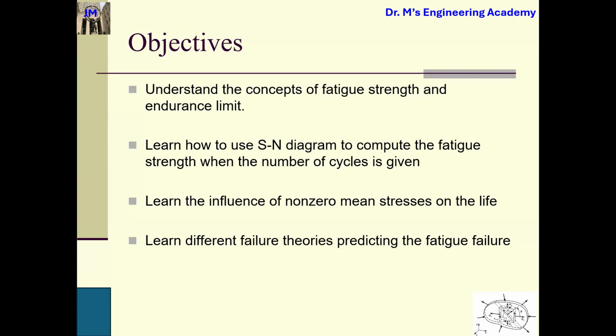For static loading, we compare the stress level with the yield stress level, and the critical stress intensity factor with the actual stress intensity factor. But for fatigue, the number of cycles plays an important role. The time plays an important role.